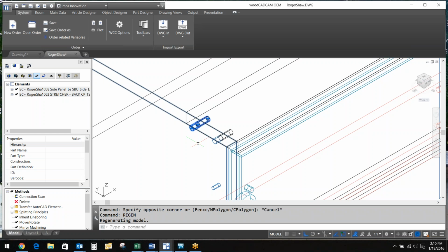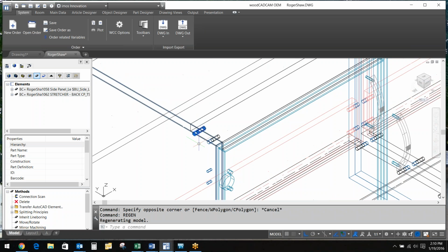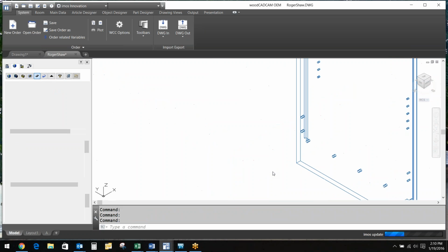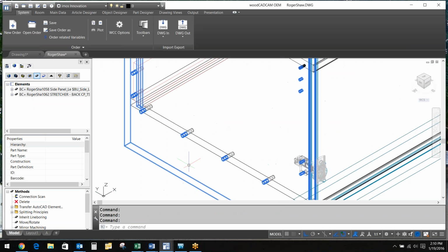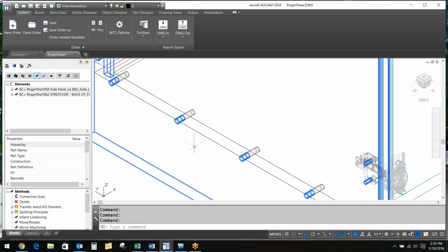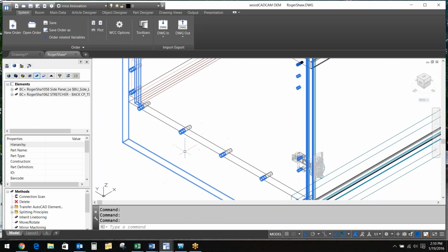What if, can you adjust the depth of the drill on the face for the dowel on the fly? For example, maybe one cabinet has a thinner material on the end panel. Yeah, so you could make your descriptor file automatically do that based on its material itself. So it would know then that it would be affected by the depth of it.